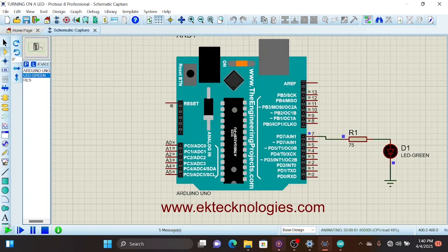You see that it comes on, goes off, comes on, goes off continuously. So it will keep doing this infinitely. It won't stop. I showed you how to calculate the value of the resistor that is used to limit the amount of current. Because if the value of this resistor is too high, it's going to block all the current flowing to the LED, and the LED will not perform whatsoever it has to perform by blinking, or it will not come on as such.